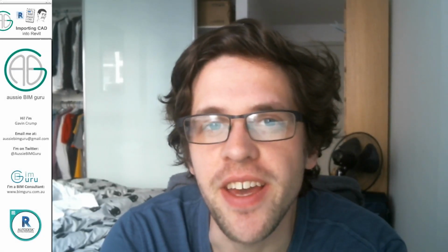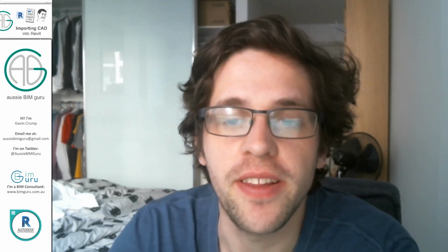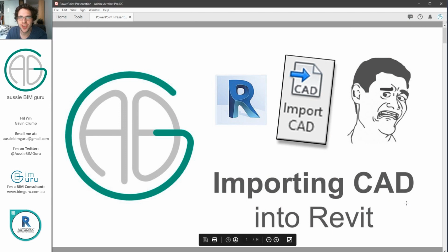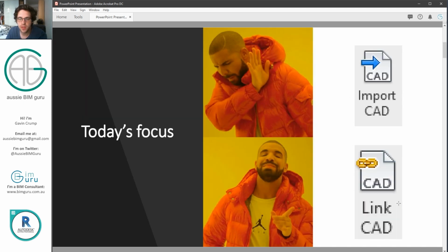Today I'm tackling a very hot topic in Revit, and that is importing CAD or importing DWG in Revit. As most of you know, this is usually a bad thing. But today I'm going to cover what you can do to import CAD properly and safely. So today's focus is looking at why you shouldn't usually import CAD. Instead, you should usually link CAD, but I am going to show you some use cases and some workflows that you can use to more safely import CAD files into your models.